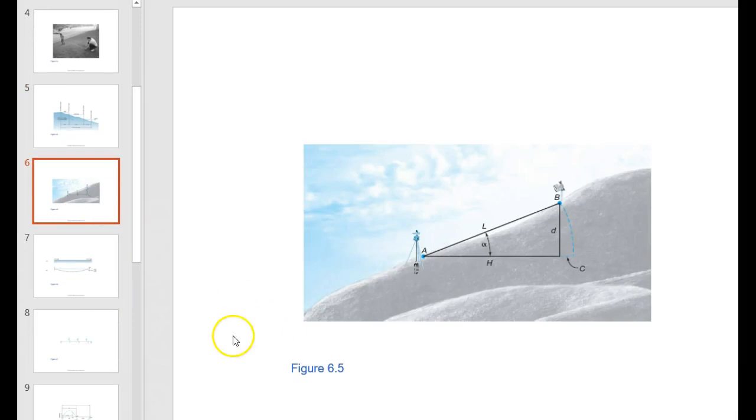So another way to compute, this is what we had talked about in the last vlog, where we have some sort of a horizontal distance h and a vertical distance d, and we can use a little bit of trigonometry to find the slope distance, or to find the horizontal distance or the vertical distance, because they are all intimately related to each other via that angle of elevation.